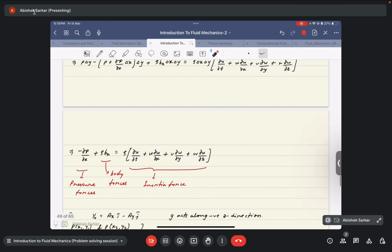Once we simplify this expression, we get minus ∂p/∂x plus rho bx is equal to rho times (∂u/∂t plus u ∂u/∂x plus v ∂u/∂y plus w ∂u/∂z), where this is a simplification of this part, and rho delta x delta y is cancelled out on both sides. Here rho bx denotes the net body forces that act on the fluid element, minus ∂p/∂x, or the pressure gradient, indicates the net pressure forces that act on the fluid element, and this acceleration term denotes the net inertia force of the fluid element.